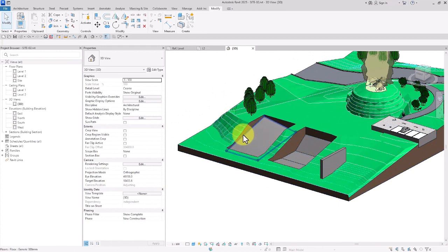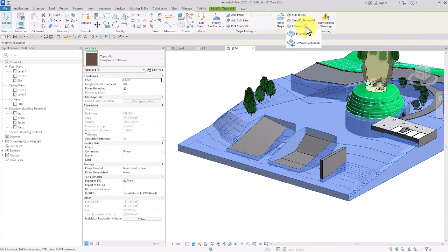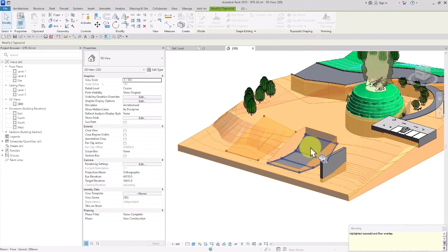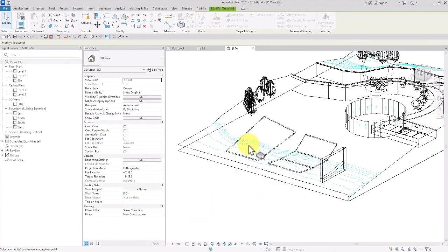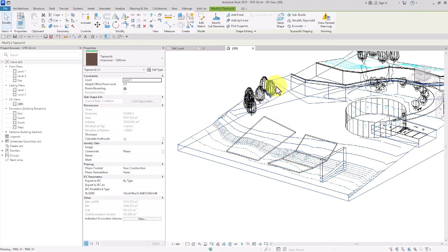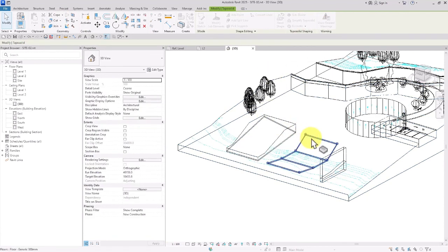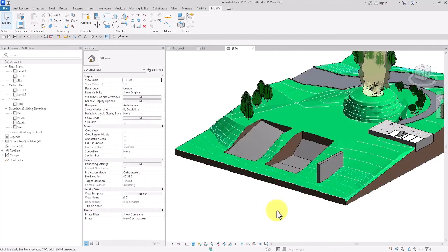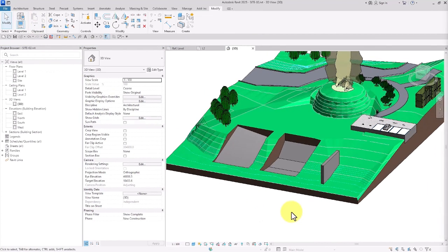Well, it's quite easy. We can just select the area, and then up here, click on Remove Excavation, and at the end, click on the area once more. And again, as always, we can easily add more excavation or even turn back the excavation that we had before using excavation itself. So excavate activated and click here. Very accurate, very simple. All right, everyone, let's move on.